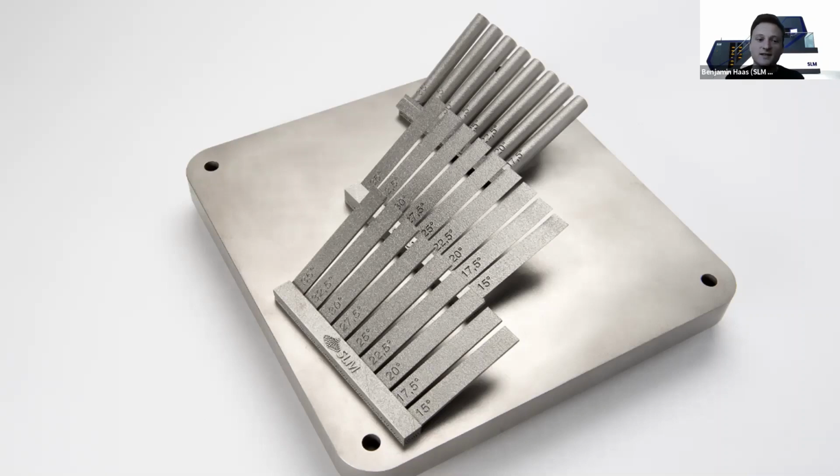And in the worst case, they could actually do harm to a machine, because we have that recoater on top of the powder bed, and if the part sticks out and hits the recoater, then this is of course not what we want. So there are basically two reasons for supports. But with FreeFloat, we have developed a technology that allows for a massive reduction of supports.